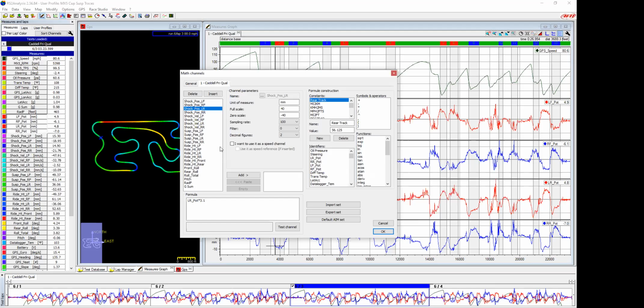It just made it easier for us as far as our math and mentally. Right, but it doesn't matter. If you mounted it however you wish, you can have 4 different motion ratios for the 4 different corners. In my case, 3.1 times: the shock shaft is moving 3.1 times more than the shock sensor.